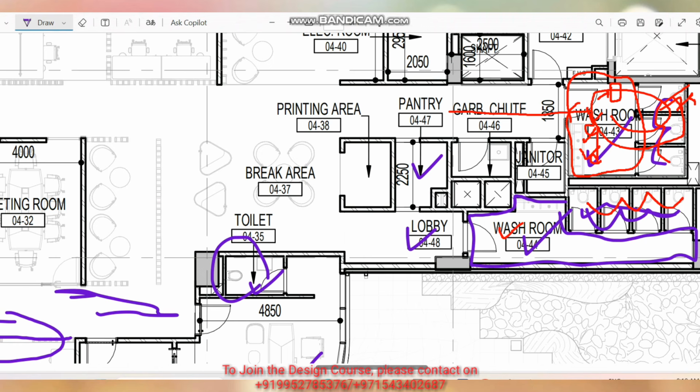Here we need 100 liter per second. So 100 liter per second, 90% of the 100 liter per second is the fresh air value. That fresh air, using the duct you can drop here by using 1 or 2 air terminals. So the fresh air will be taken outside, and to compensate the fresh air, the return air from this fresh air duct, the terminal will manage. So we don't need to consider the exhaust for the small area.